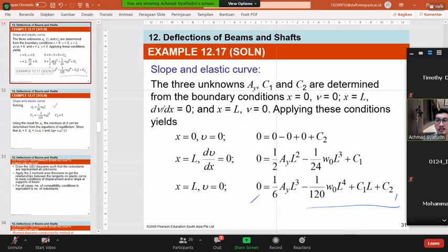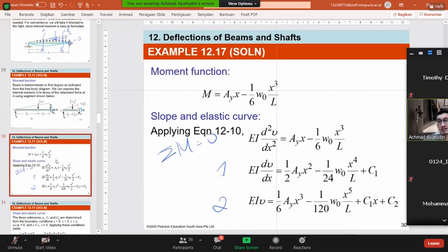The equation is this number one and this is number two, beside the rigid body or free body diagram equilibrium. Actually, this is number three formulation: number one, number two, and number three. So you have three formulations, three equations, to solve the unknowns in the indeterminate problem.